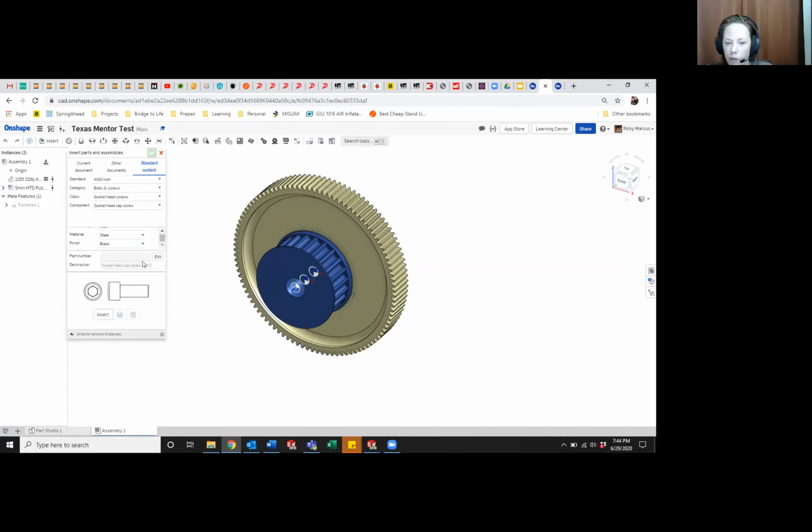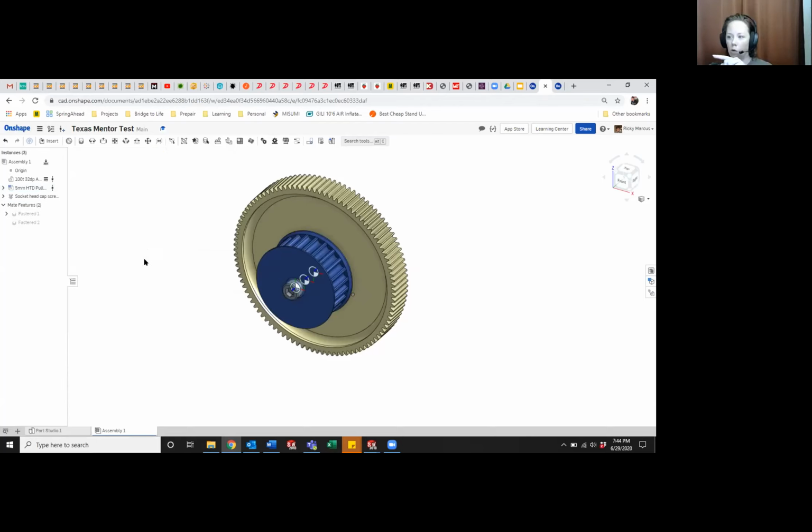And the other really cool thing about this is it's not just I take one bolt and I constrain it, which in Inventor is like 3 constraints or 2 constraints to get it in the right spot. This is one constraint to fasten it in place, then you can duplicate it. So basically, if you have a surface that had 6 holes on it, you could select that surface and it would drop them in all of those holes.